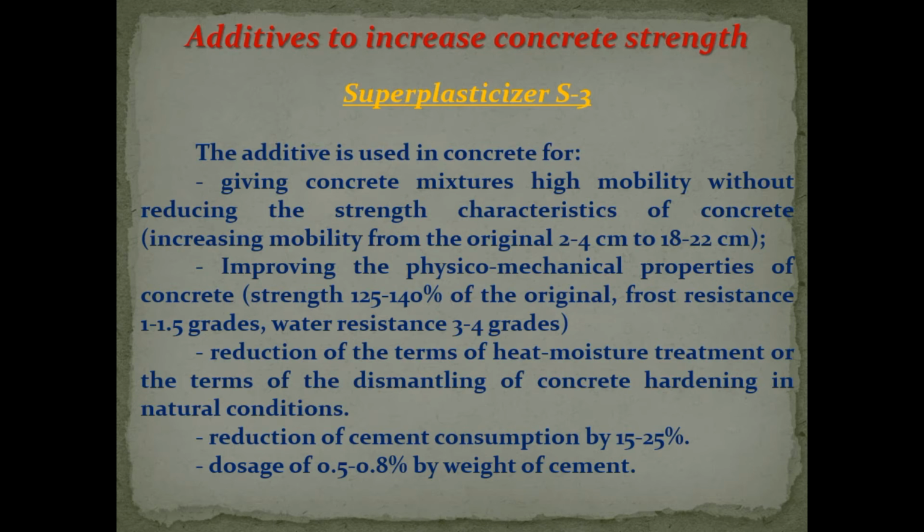of the original, frost resistance higher by 1 to 1.5 grades, water resistance by 3-4 grades, reduction of the term of heat treatment or of the dismantling term for concrete hardening in natural conditions, and reduction of cement consumption by 15-25%. Dosage: 0.5-0.8% by weight of cement.